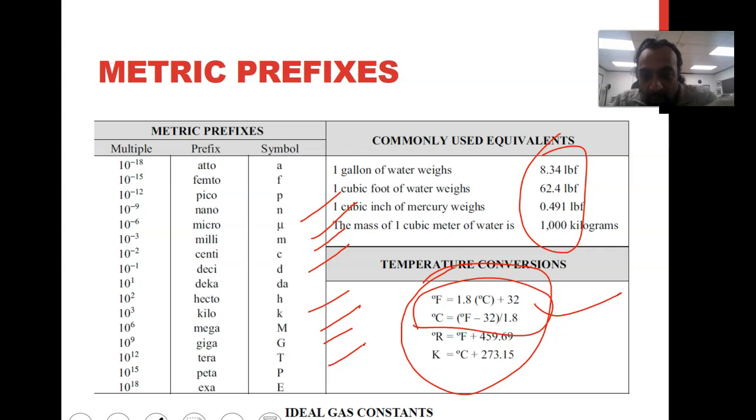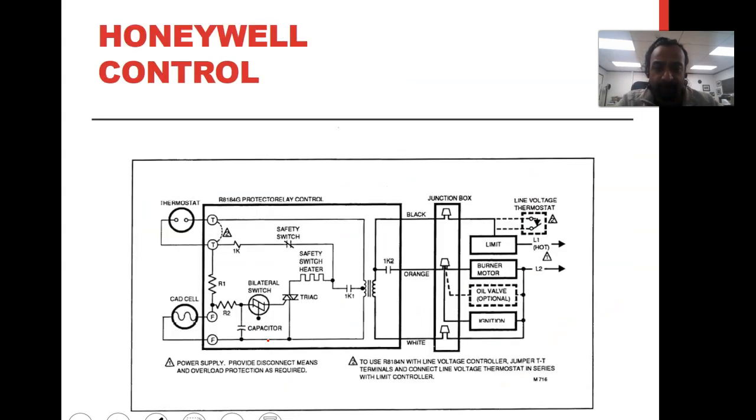But it's good to know what they mean, especially if you are going to do a lot of measurement. I mean, micro, you'll see microfarads a lot, so be aware of this symbol in here. Milli, you see that a lot. I don't think you see centi or deci that much, but you do see K for kilo or mega. Sometimes these are interchangeable. Sometimes mega means 1,000. I don't know why, but just double check the manual for each equipment you use and what they're referring to.